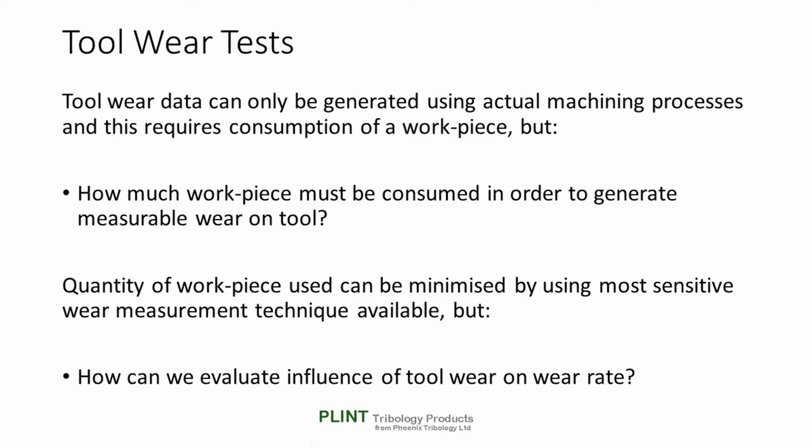In general, satisfactory tool wear data can only be generated using actual machining processes, and this obviously requires the consumption of a workpiece. The issue here is to work out the quantity of workpiece that must be consumed in order to generate measurable wear on the tool.